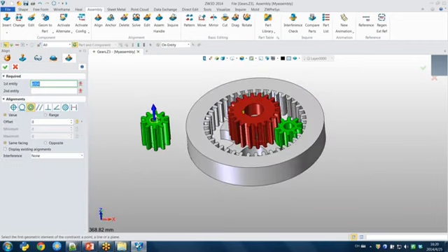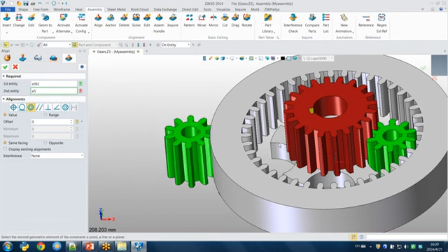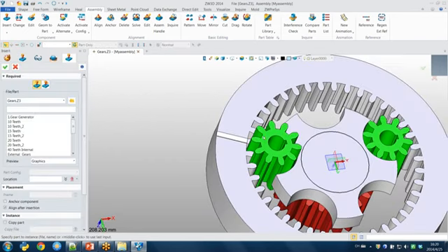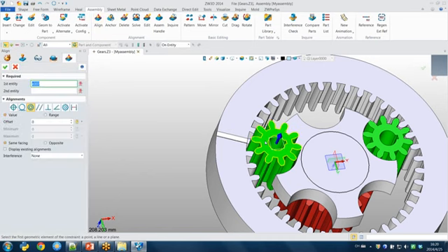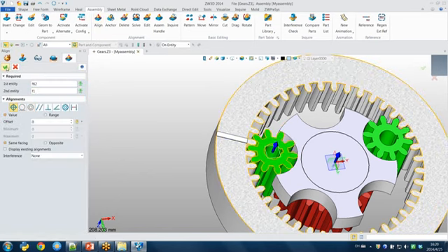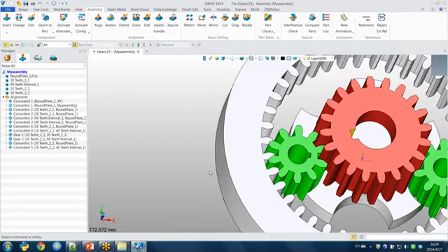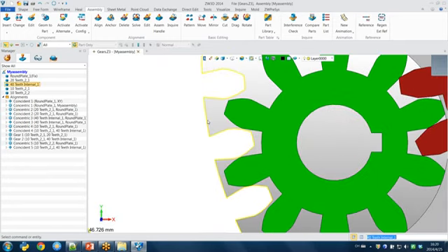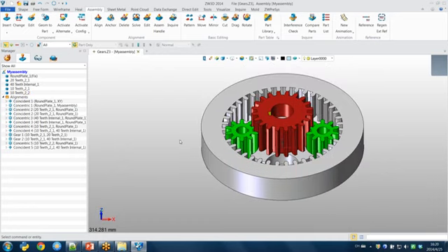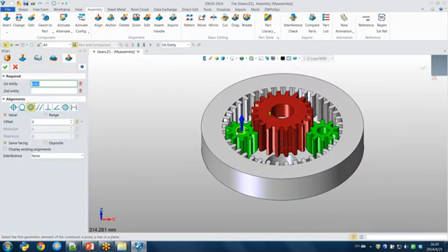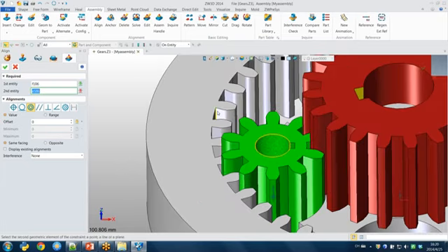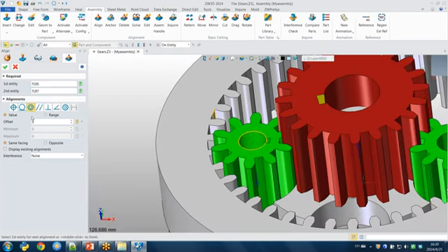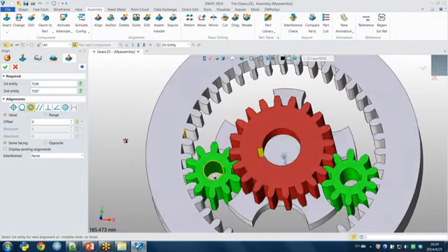Select the insert the teeth and select the edge, same face. Okay, and for the bottom, the same alignment. Choose the 2 surfaces. Press OK. So let's check the position. Oh, it's good. So I can align the key and select the surface. Select the surface and the value. Okay, let's check the direction.